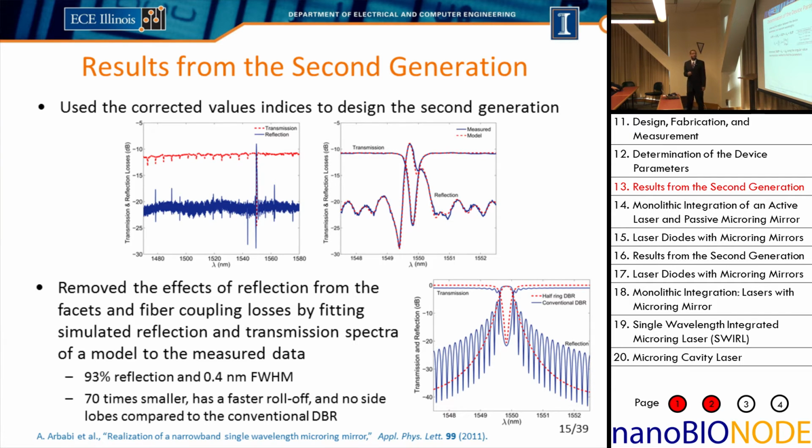So we determine the refractive index of the core with a precision of essentially 4 decimal places, the cladding to 3 decimal places, and then the core thickness to, it looks like, 1 decimal place, and the dispersion to essentially 100%. It's not very accurate.